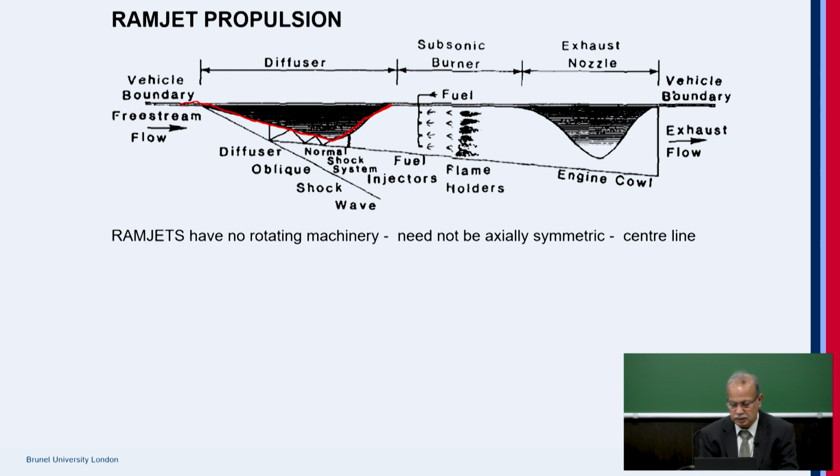It must be convergent divergent for a RAMJET operation. The most important thing you see here is that mostly it will be a mixed compression inlet because of the Mach number at which it travels. And then you see, this is very important. This is what is called a terminal shock.